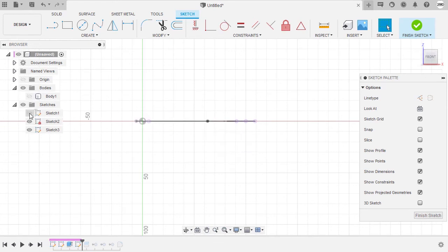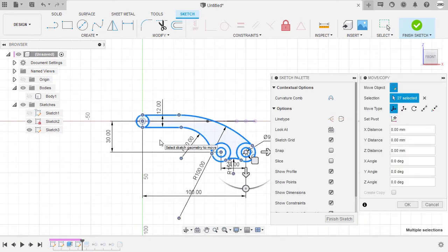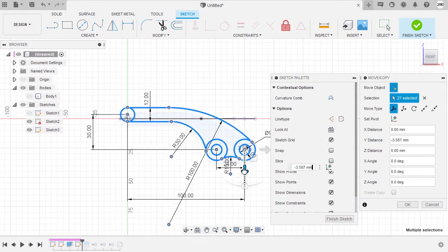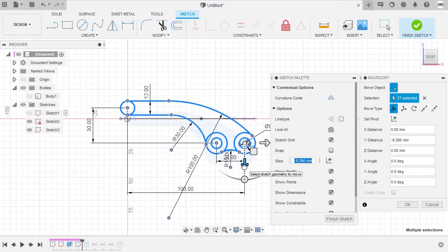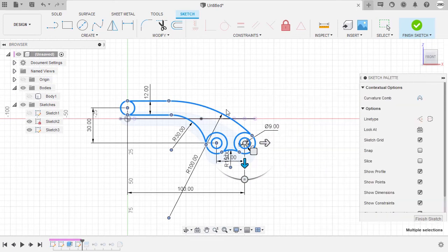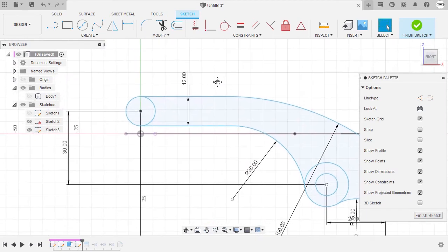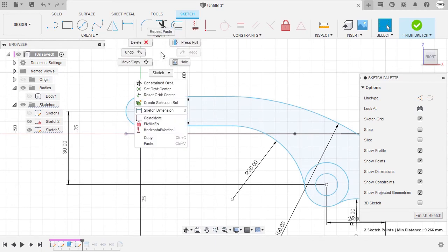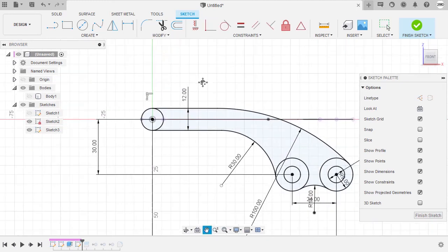And sketch 1. And this time, I'm going to hit Ctrl-V to paste. Let me move this up for me to easily apply constraints. Selecting OK. And finally, I'm going to have this point and our origin with both of them selected. I'm going to right-click and select Coincident.